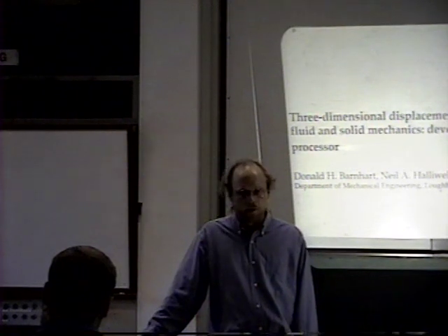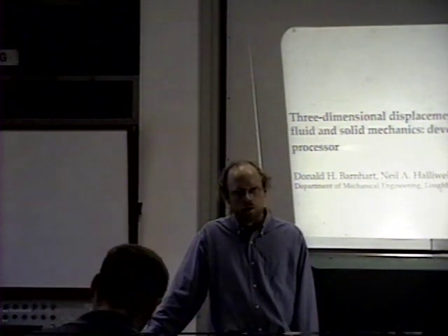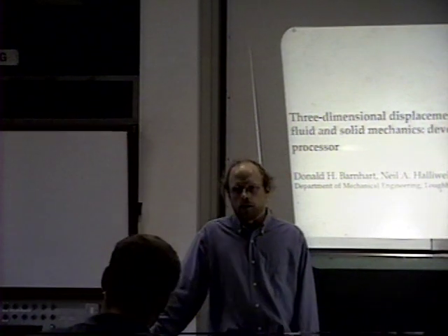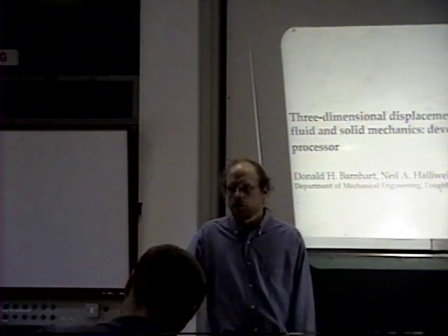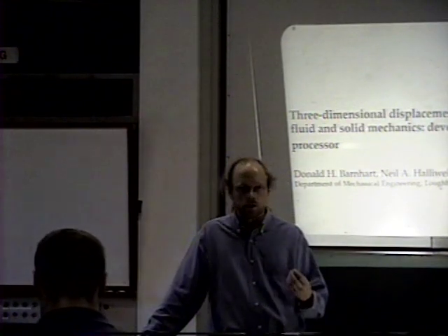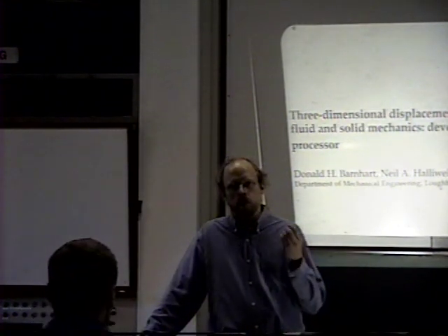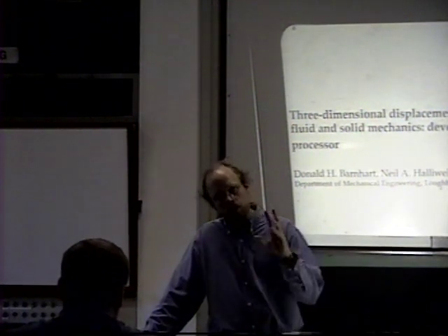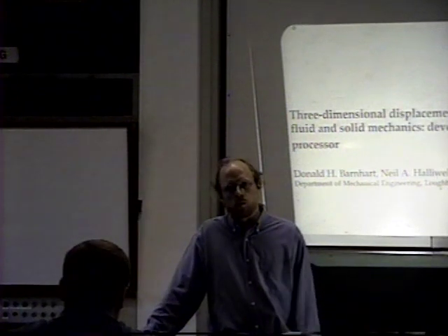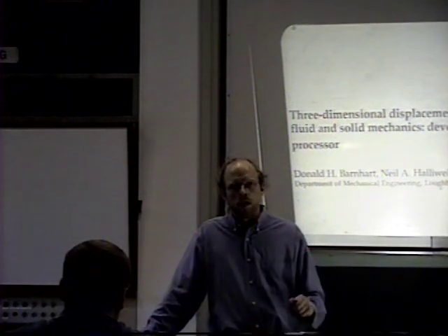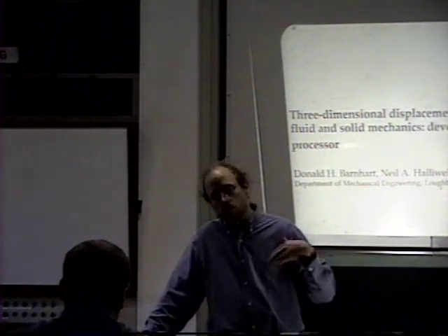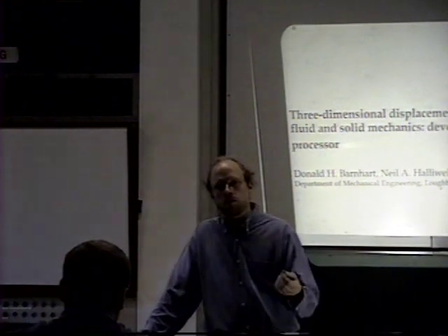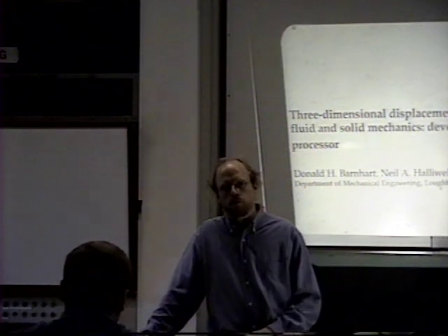Maybe I should back up to explain why do holographic PIV at all. What we are able to do is take simultaneous measurements in millions of locations within a volume in one instant, and then measure the three-dimensional velocity field of that volume.